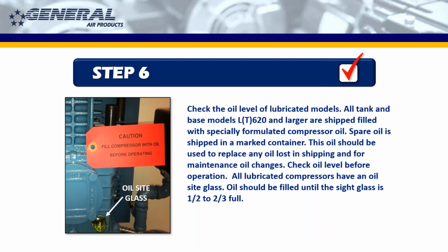Like I gave you the spiel already on the oil that comes with it. We do sell oil, and if you call in, I believe it's 30 weight non-detergent is what we use. We have specially formulated compressor oil if you want to buy ours, but I'm not in the oil business, so whatever works for you is fine by me. But do call, because we do have some with a few different weights. So if you're looking to replace oil, certainly you can order it from us. But you can also go to your auto body store and buy some. Just make sure that you call us up first, get the model number, and give us the model number. We'll be able to tell you what oil to get. Like I said, most of the time it's 30 weight non-detergent.